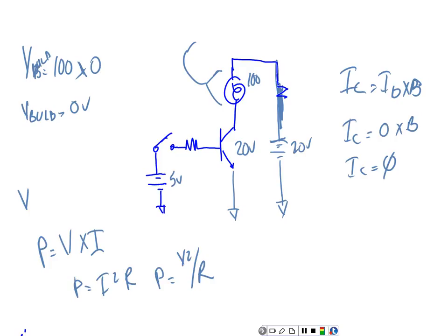So here we're concerned with that IC current that it can handle. And then we're concerned with how much it can block collector to emitter when we do what? When we cut it off. So that's what we're turning when we do saturated switches. And we're not really concerned with the power rating of the transistor because when it's saturated, it's almost producing no power, right? You understand? And when it's cut off, it's producing no power. So we worry about the power rating when we operate the transistor in the active region.